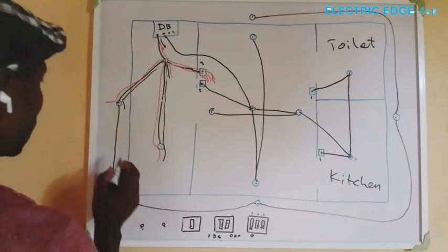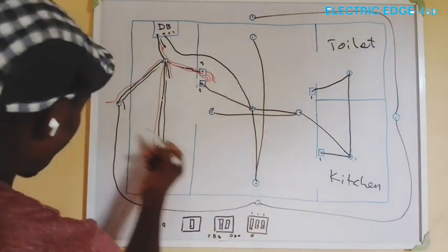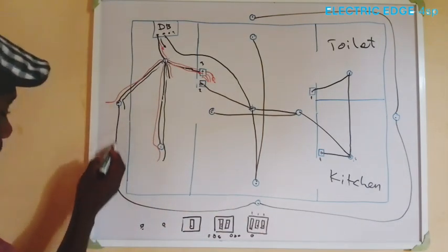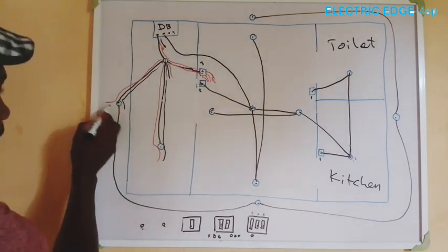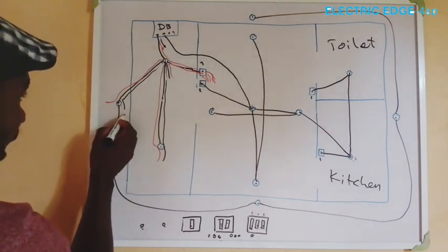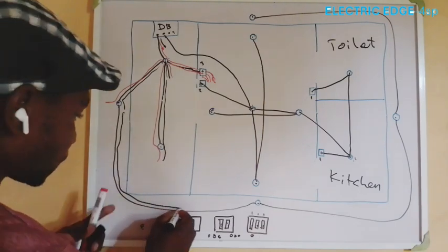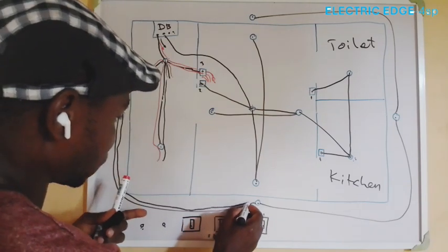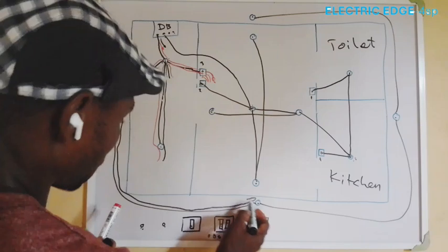If you like, you can continue this red. You can put your fishing tape from here, and when it comes out at this point, your red can continue as a loop. You can continue your red, or you cut this red, put another red, cut the black, put another black that will follow inside this pipe. Remember, this second routing is following the pipe, it's inside this conduit pipe. This is where it will stop again, and you reserve for termination.